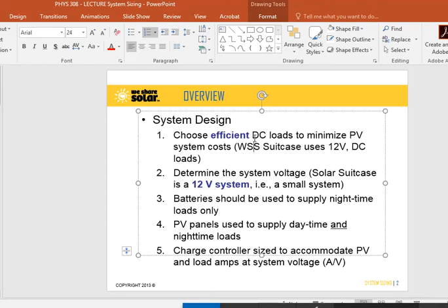For those of you working with a bigger scale, you might ultimately consider whether it might be more appropriate to have multiple charge controllers broken up into smaller pieces rather than having one huge photovoltaic grid, in which case the cost is going to increase, but you might try to think about where is that balance point? What's the balance of all those parameters?